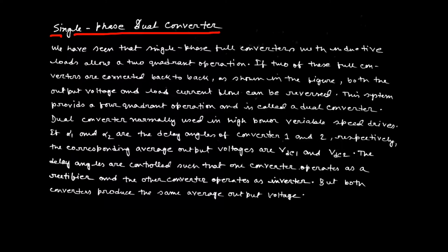When the inductor starts storing energy inside it, it can provide the first quadrant operation in which the voltage and current both are in positive direction. In case of 4th quadrant operation, when the inductor starts discharging, the current is still in positive direction but the voltage appearing across the load is in reverse direction. That is why in the first quadrant operation the power is transmitted from supply to load, and in the 4th quadrant operation the power is delivered from load to supply.